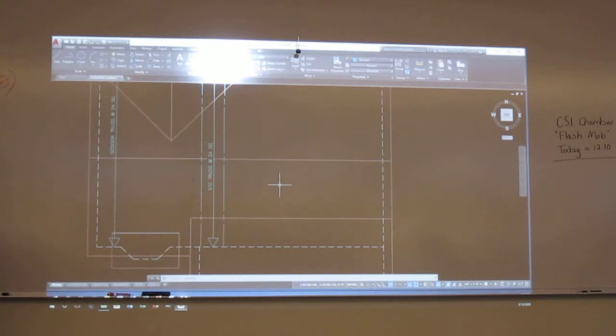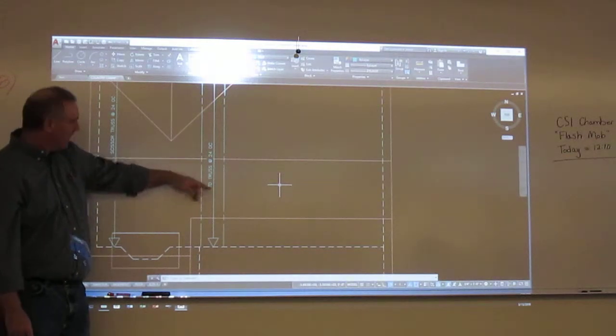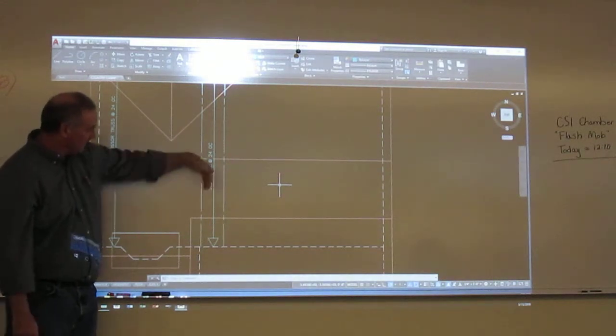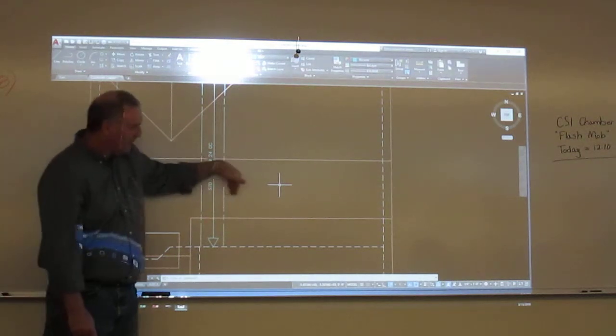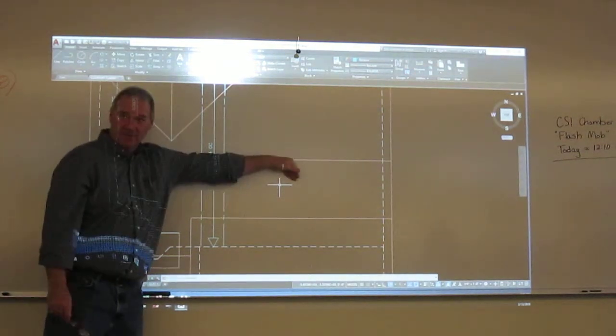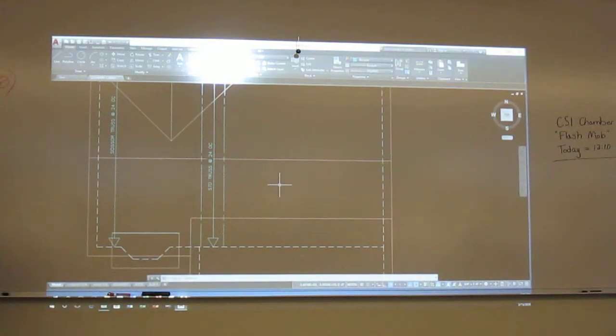Because we're gonna change our truss shape. These are all gonna be scissor trusses from here to here. And then from here, they'll put in a couple trusses that have a flat bottom, standards. Now here, I'm gonna go back out to a different type of truss. Okay. So all we have to do is just kind of look at our underneath and upper top of the ceiling, give them the shapes and where we want them.